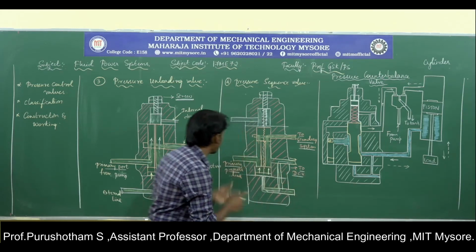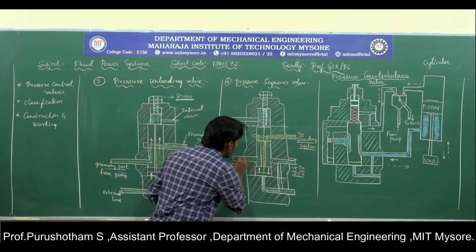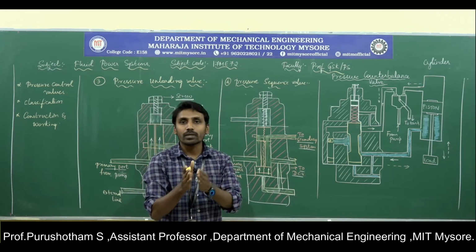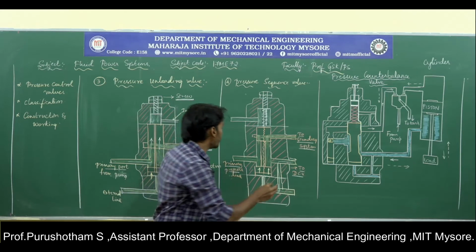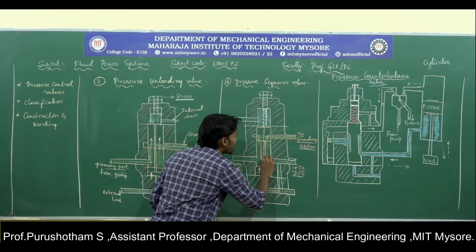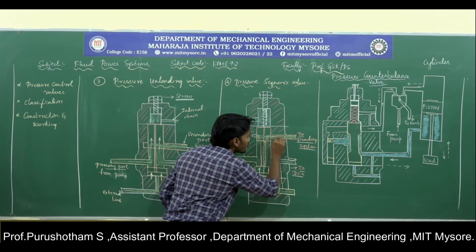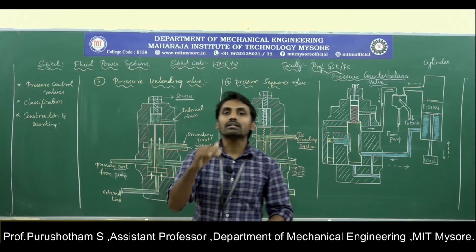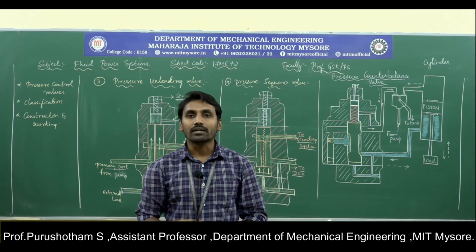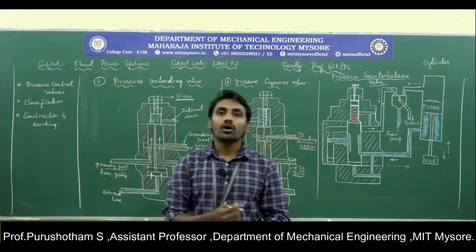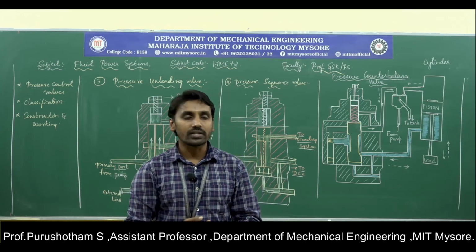So here, continuously the fluid is transferred to the direction control valve, which has to clamp the sheet metal. In the meanwhile, due to the back pressure, the piston movement takes place, due to which the fluid also enters the secondary system, which causes the bending of the sheet metal. So by using this we can carry out the sequential operation in a hydraulic circuit.